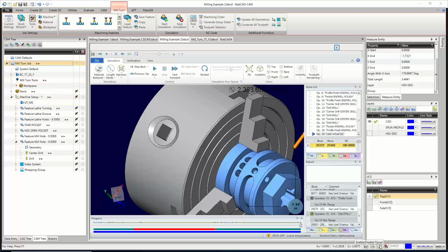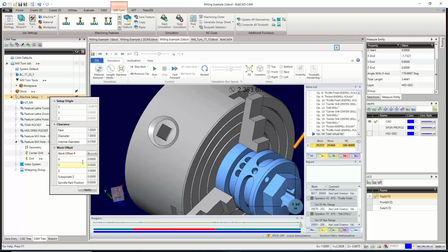That's how you could turn them on and off. I love having them because I can go right here to the machine setup, click on those arrows, and then right here for my work offset, I currently got it pulled out 5 inches. And that's now the problem: it's 5 inches off of the face of the chuck, not from here. They don't count the faces of the jaws as 0. So if these are 2 inches or so, I only got about 3 inches of my part sticking out. That would be the 5-inch total.